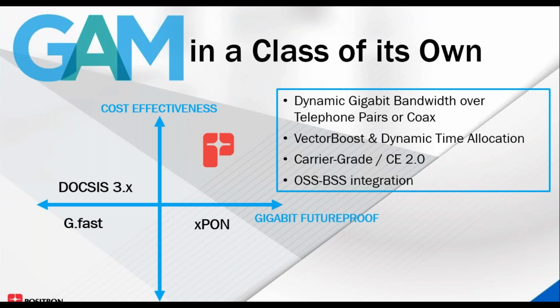It's better in terms of cost effectiveness compared to DOCSIS 3.0, 3.1, which was kind of the leader up until then, and far better than G.fast or DOCSIS in terms of bandwidth. For bandwidth, it's on par with GPON. What you can deliver today with GPON, you can achieve the same bandwidth over G.hn. But you don't have the impact of the splits that you see with GPON, where everybody shares the same backhaul, so they're limited to an aggregate maximum of 2.5 gig down and 1.5 gig up.